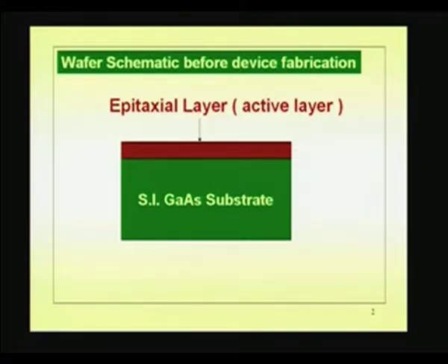But today, with the ability to grow high purity gallium arsenide with the compensation of the EL2, you do not have to worry. You can straight away grow the epitaxial active layer on that. Now, what we want to discuss today is about this particular layer.